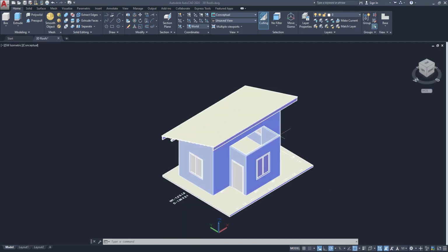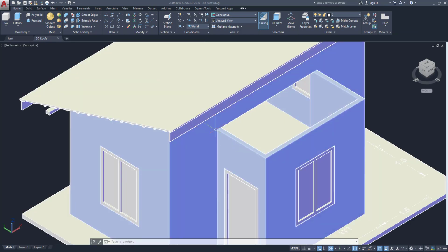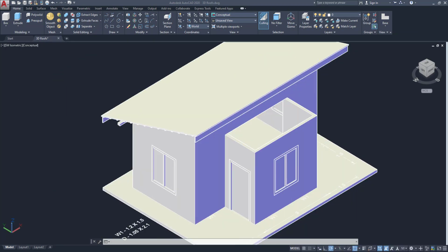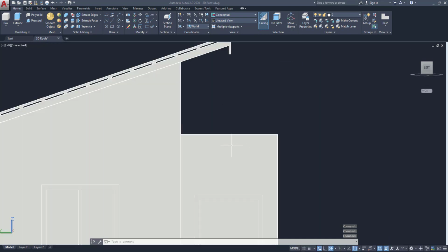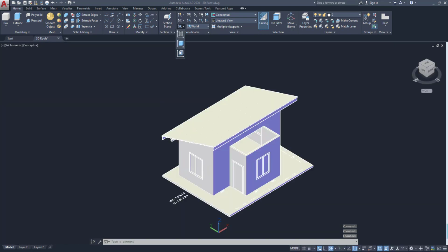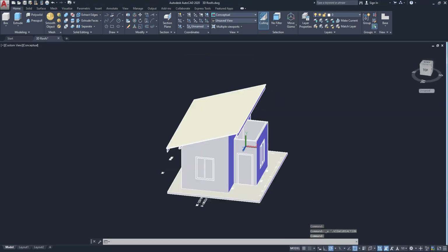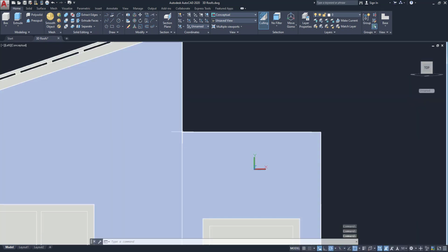Here we have to complete this part. So I decided to place a slab here. Go to left view, change the view, go to face, go to use UCS and change the face and place it here, go to accept. In this view I am going to change this part. So I have to model my slab.